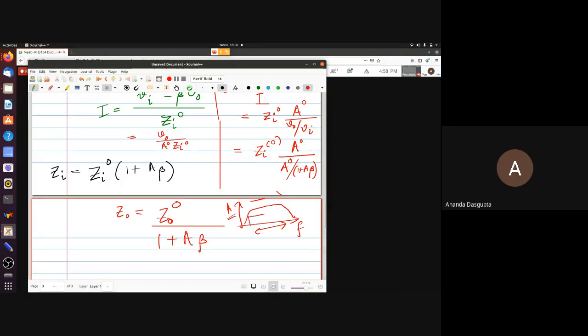So just as for filters, you look at those frequencies for which the gain falls down from the flat peak value by a factor of √2. √2 again, the voltage gain falling down by √2 means power gain falls down by a factor of 2, and that's the 3 dB frequency, 3 decibel. I hope people still remember that much from the theory of filters that we talked about a long time ago, near the beginning of the course.